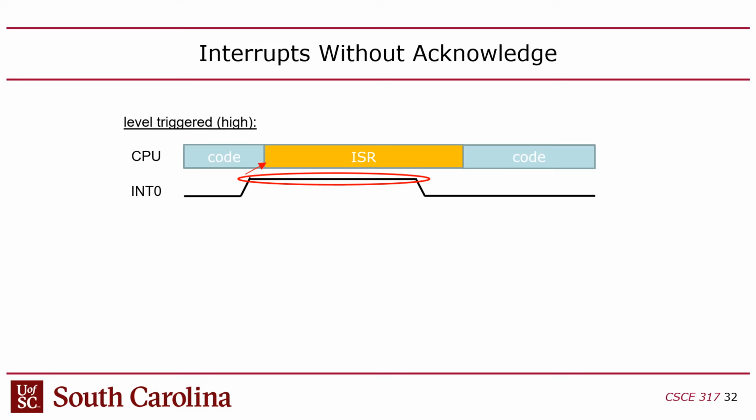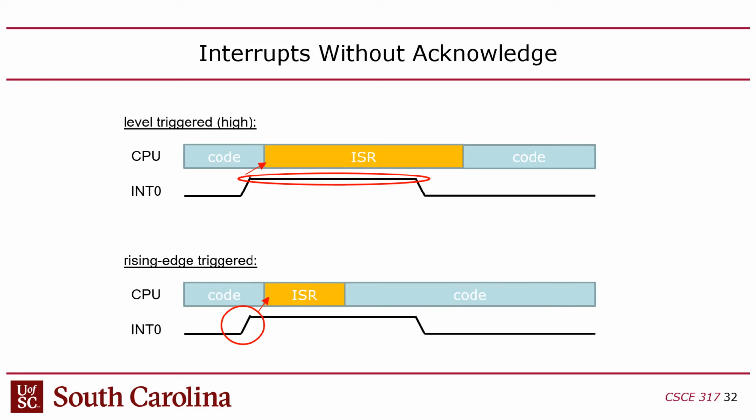Likewise, the peripheral doesn't even know how long it's going to take to run the interrupt service routine, right? Who knows? Maybe the CPU generates a page fault or something, or maybe, like with Linux, there are queued interrupts, so you can have several pending interrupts at one time, right? So this is also non-deterministic. The basic problem here is that the peripheral doesn't know how long to hold that high. It just has to guess, right? Now, if you have a simple system like the Atmel 328, that's the Arduino, that's exactly how it works. The peripherals in the Arduino just kind of have to guess on this stuff, right? Not a great system. And it leaves some problems here that can happen.